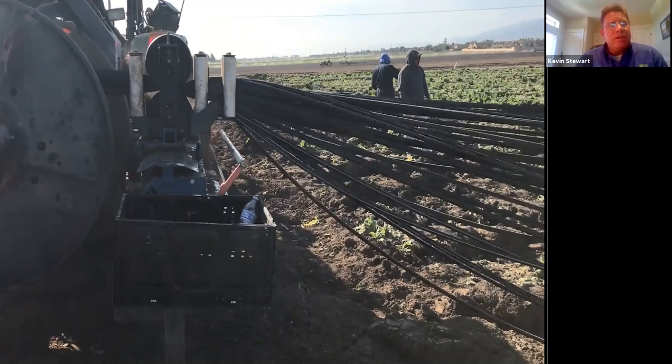This has really been a good option, and I will say, there is a chance, year after year after year, you can see a little bit of degradation with the tape. Maybe something gets plugged, or as you're splicing, you don't get it just right. This way, you're starting fresh, and you're really getting 90-95% uniformity out of the drip tape. I think studies have shown, regardless of whose tape it is, the performance goes down year after year, especially in a situation like this.